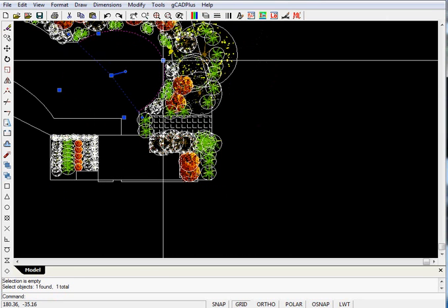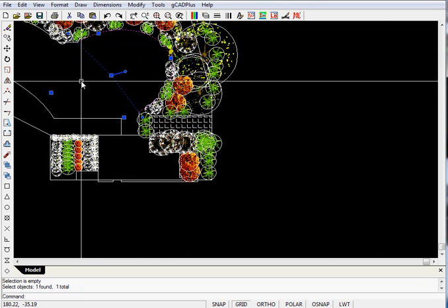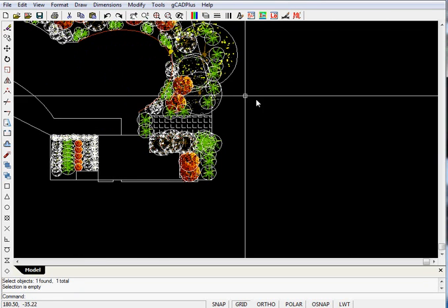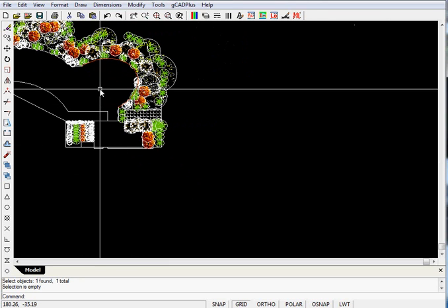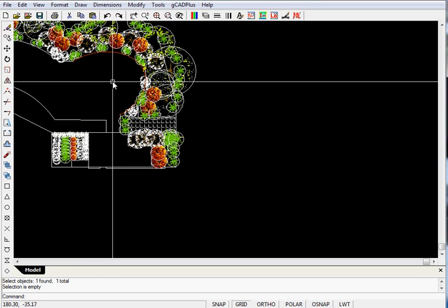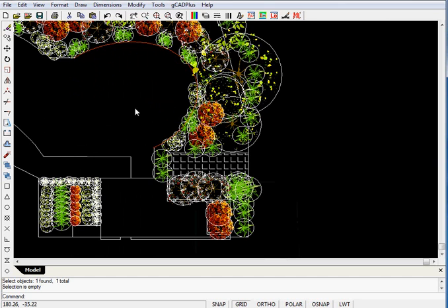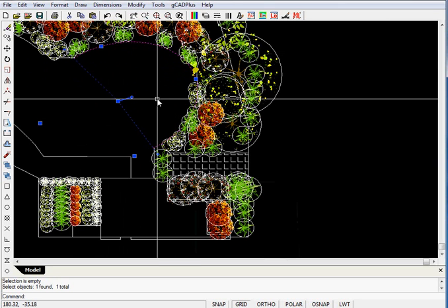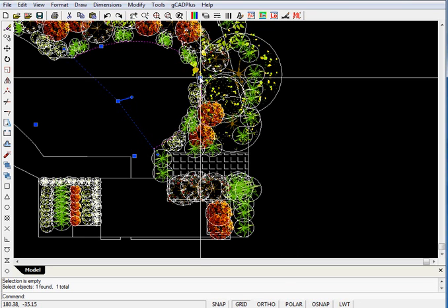We can still play with that shape if we want, bend it out just a little, and it stays anchored at the points that we want. So now maybe we've got a shape that more closely matches what we were after, without the little jink in the polyline that was previously there. You still have control over what remains of that ellipse. You can click it here. You can move it in and out and bend it just a little.